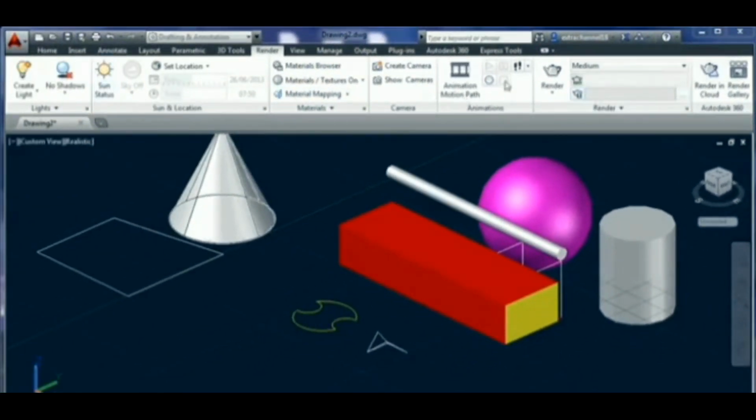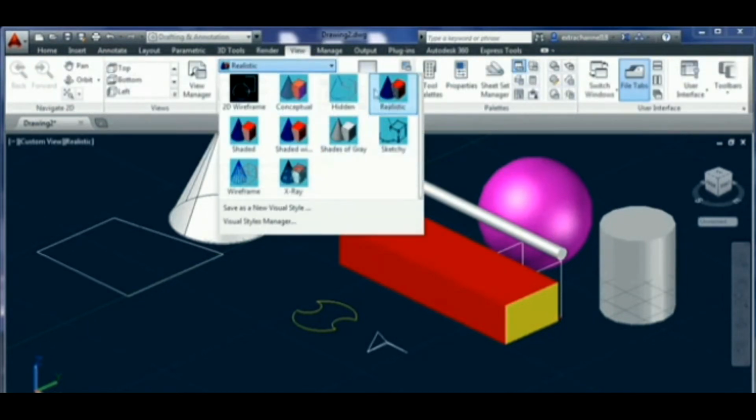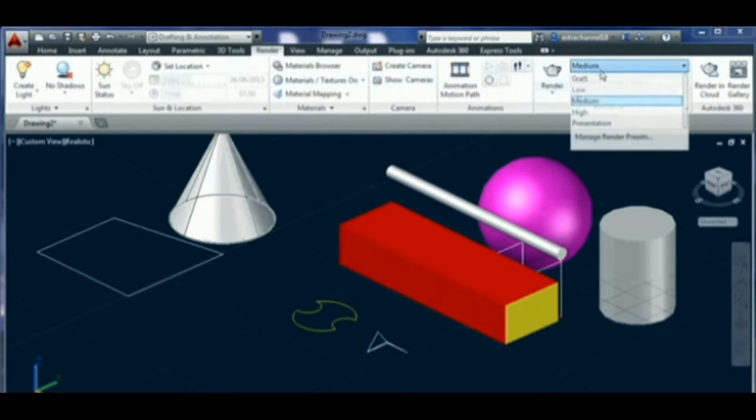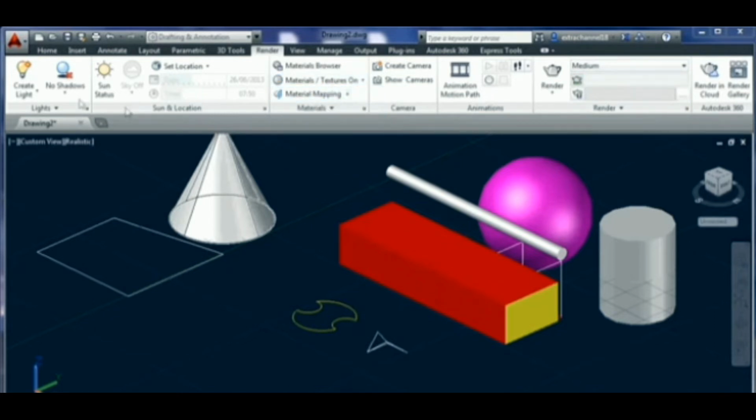This window contains all the render options to view better your project. Make sure to choose the realistic visual style in View window first. You can choose options through this window the best way you want. This is done because for complex projects, it can be a problem to render fully your work, with full quality, full shadow and full textures. For this reason, it is important to choose the way to render all.